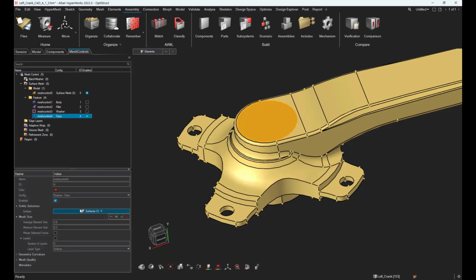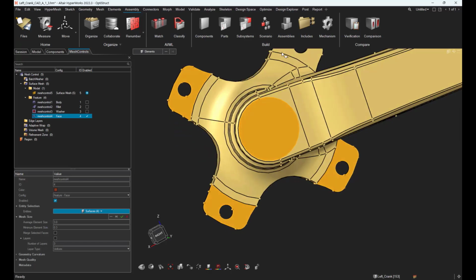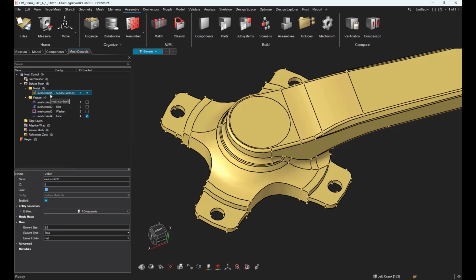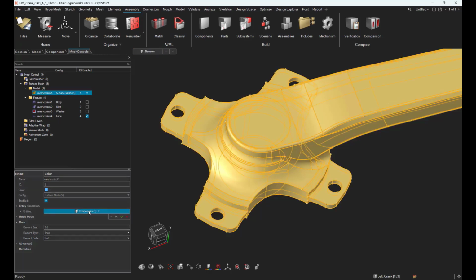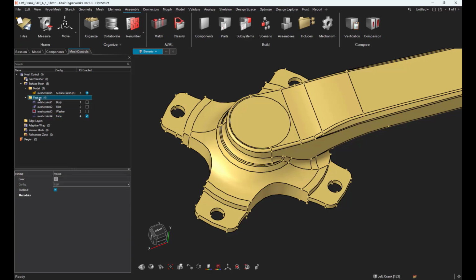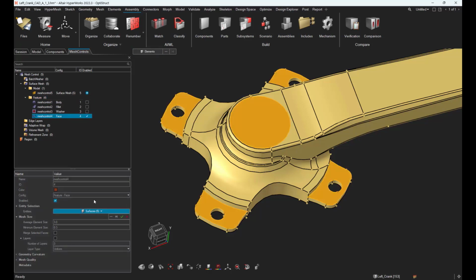And let me add in the feature mesh control some other surfaces, that one. Okay, so we've got one body mesh control that will use the HyperMesh algorithm, the size N bias, on this component, and we ask for a 5 mm element size. And we have one face mesh control. It is a feature mesh control coming from SimLab, and it is assigned to these 5 surfaces.